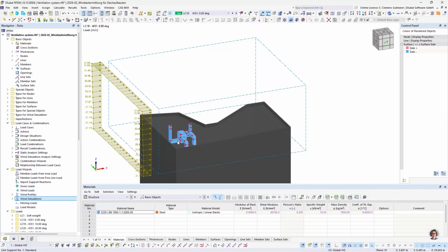And here is something important to know. Since we have the original model and we have the shrink wrapping hull, let's say, there's a gap between them, and we have to transfer the loads that are calculated to the original model. So there's a small error during this transformation process.